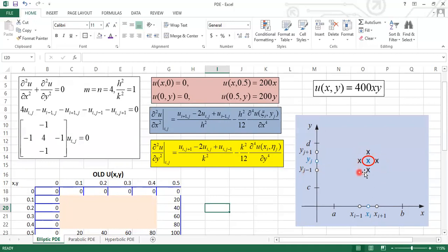So when we provide these equations in the main equation, this defines the differential equation in difference form at point ij. So our point of interest is point ij. The value at point ij will come from the surrounding 4-point values.